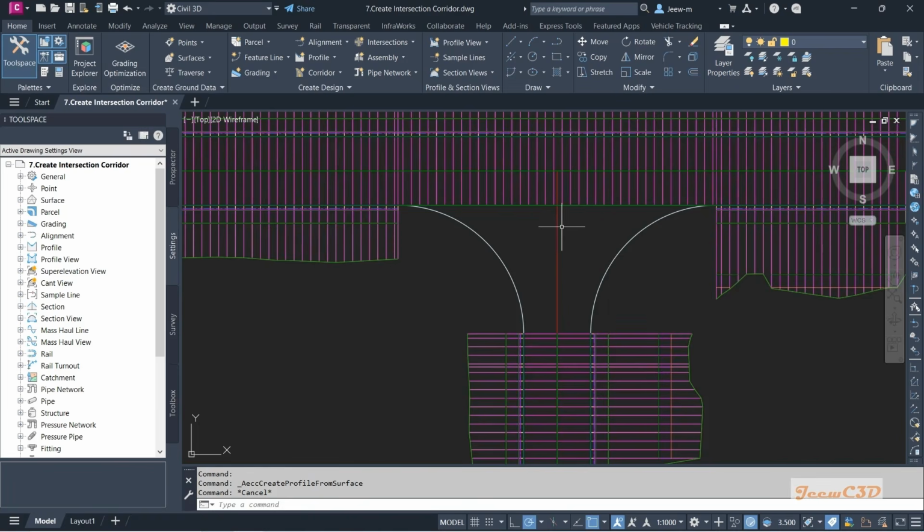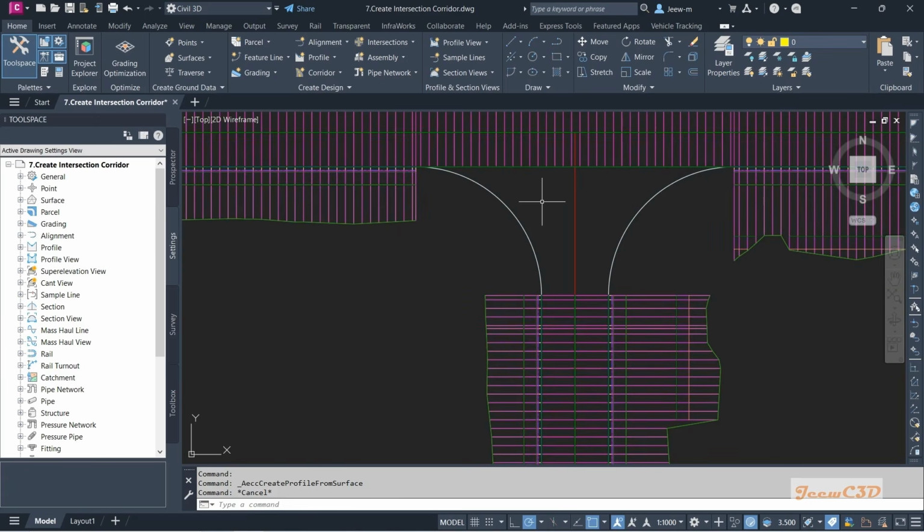When you are going to create these curve return corridors, the logic is like this: from here until this point, we will have the corridor. The assembly is coming from here, then it is targeting the elevations on the secondary road. After that point, it will go like this, and it will target the elevations and also the width. In this case also the width and elevation, in this also the width and elevation.